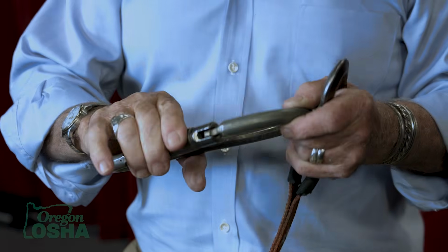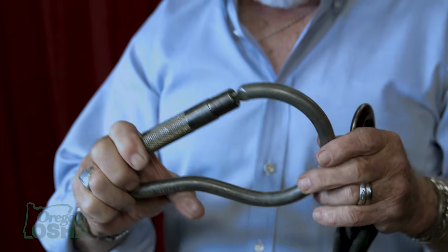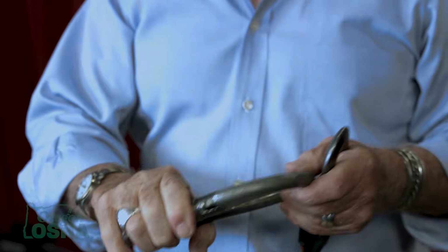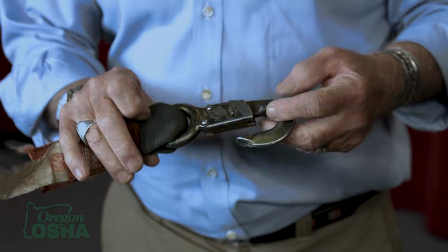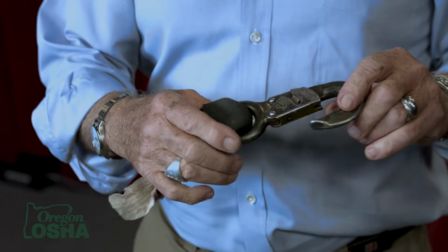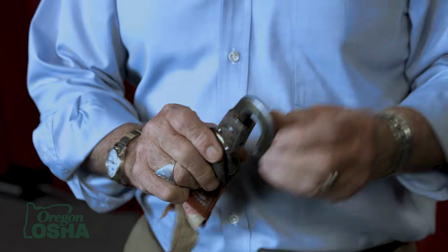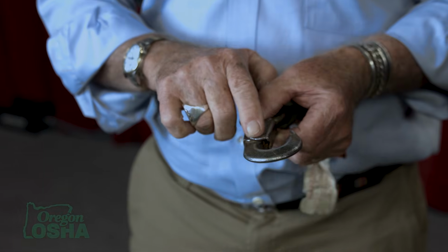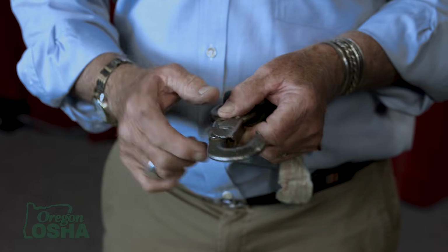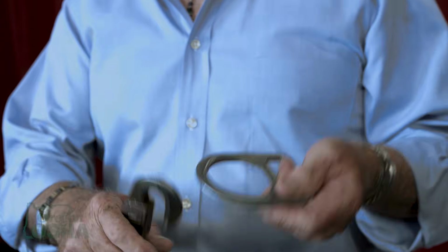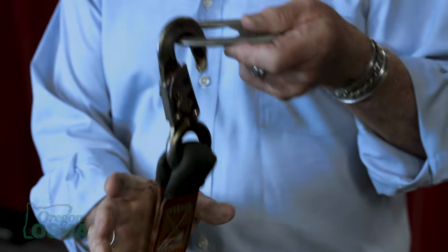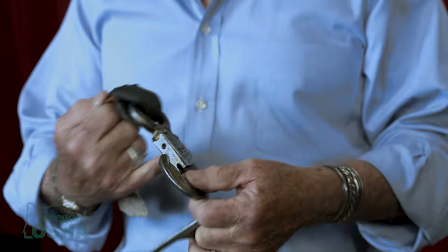So defective components that create an accident are easy to inspect following the accident, so simply use them. Components have to function. Here's a snap hook that was part of an actual accident, and if you look at this snap hook down this parallel, you'll see here the impact where somebody hit it, so that working with the D-ring, all he had to do was hook it up without manipulating anything. No closure. Recognize too that easy on, easy off. You've got to have that closing gate to make that a legitimate component.